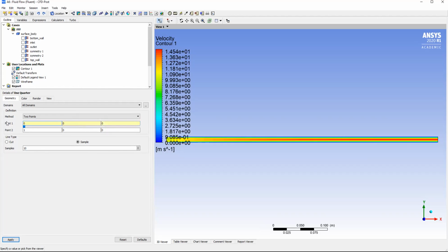So the way that it works is that first you go to 0.1 and you decide, okay, where do I want 0.1? Well, this first line, I want it to be 1/4 of the way along the pipe. So I want it to be 1/4 of 0.5 meter. So I am going to stick that on 0.125, I believe. Let me make sure that I am correct. Yeah, 0.125. So this is on the x-axis, it's going to be 0.125, somewhere maybe around here, meters into the pipe. And 0 in the y, meaning that's just going to stick right on the bottom of the pipe here.